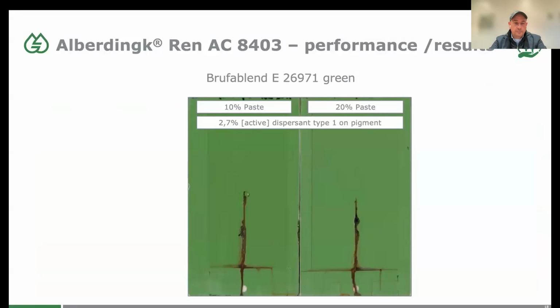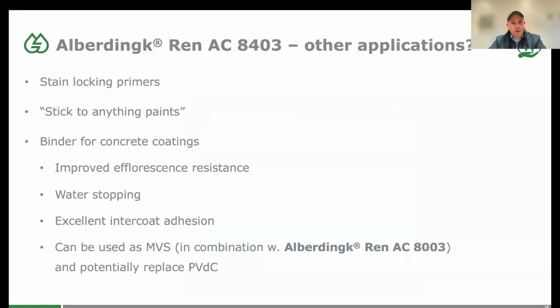Lower levels of organic pigment help to maintain the fantastic barrier of the film. If you try to use conventional pastes, or conventional pigments, you are probably never going to achieve the same result, because there is no dispersant that would be able to stabilize the pigment and be hydrophobic enough not to harm the barrier of the polymer dispersion.